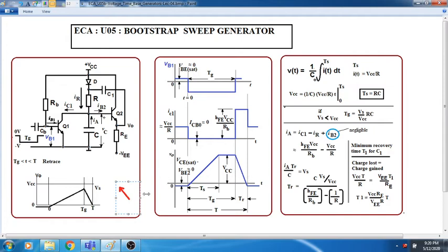Okay. Now what we have to do here is understand one more very important point, that is you can see here this capacitor C1 is the main source of charge for the resistor here for supplying the constant current. Now what is this capacitor doing? This capacitor is quickly charging using this VCC and VEE to store the charge so that it will be able to supply the charge right from the time the trace is starting here and then trace is ending.